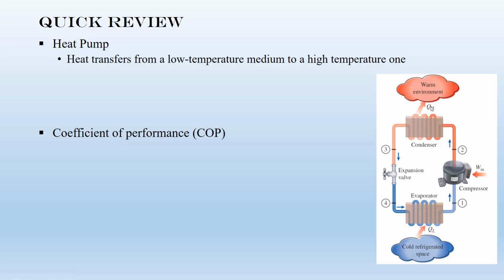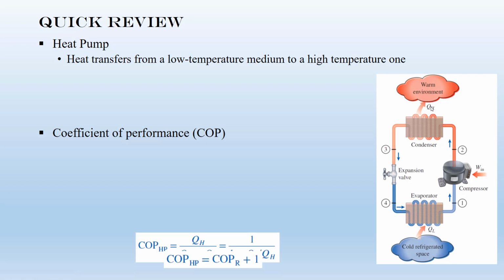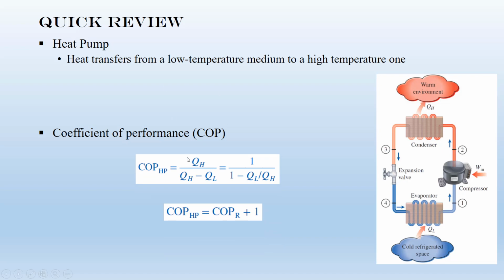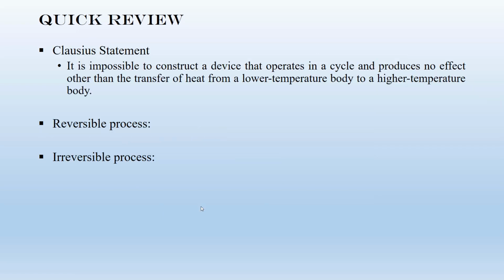If you use the definition for the efficiency, then you can prove that the COP, the coefficient of performance, for a heat pump can be determined from this equation. If you compare the COP of a heat pump and a refrigerator, you can prove that there is this relationship between the heat pump and refrigerator COP. Then we discussed the Clausius statement of the second thermodynamic law.